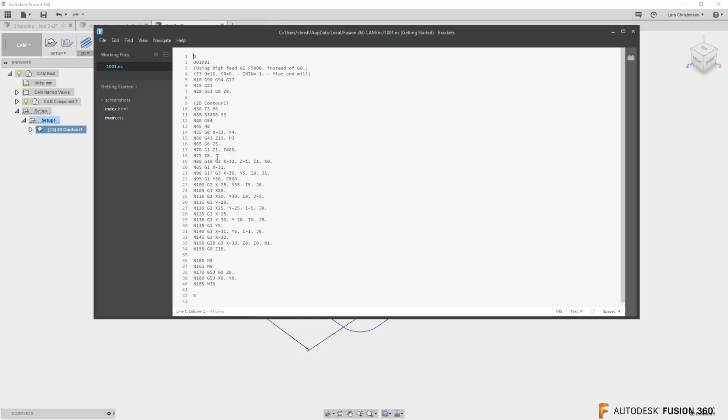You will actually see that when this one comes in, it's gonna move over in X31 to do the lead in. Well, I should probably start from the beginning. It's gonna come down to C0 because we're just driving the sketch. It's gonna turn the lead in, lead out on, and it's gonna walk into the part.